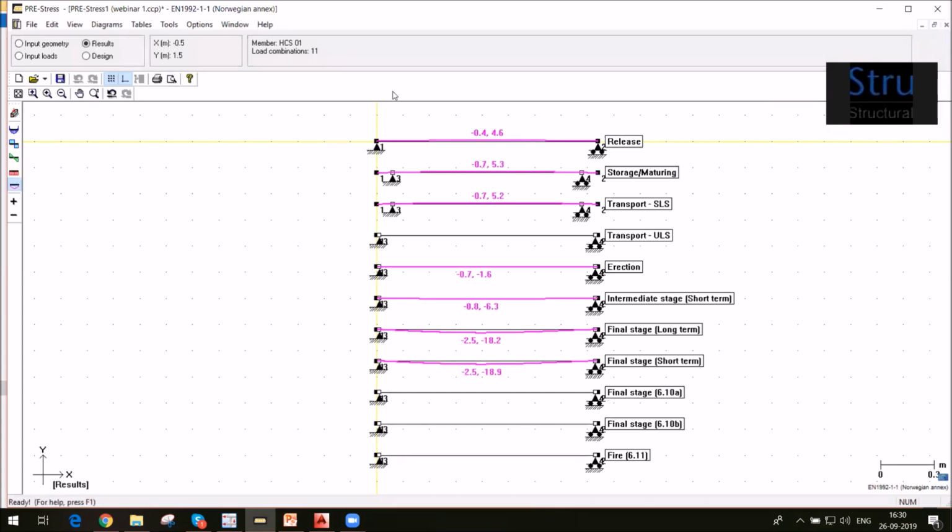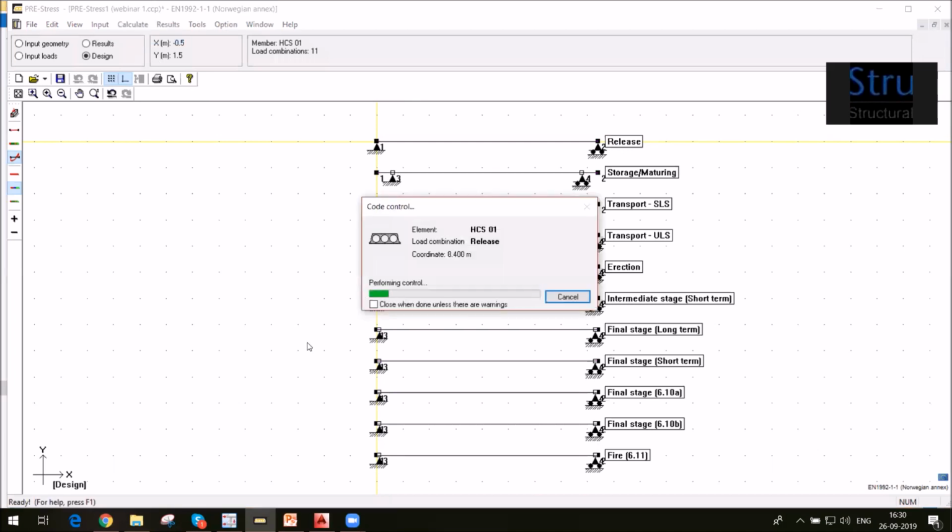Then we click on design. For continuous beam, do we have a limitation on the maximum number of spans, and does the software take into account pattern live load? No, the software doesn't take into account the pattern live load, as we are giving the input. But yes, we can have n number of supports in it for the continuous beam. We don't have the live load pattern itself, so we have to create it by creating different load cases.